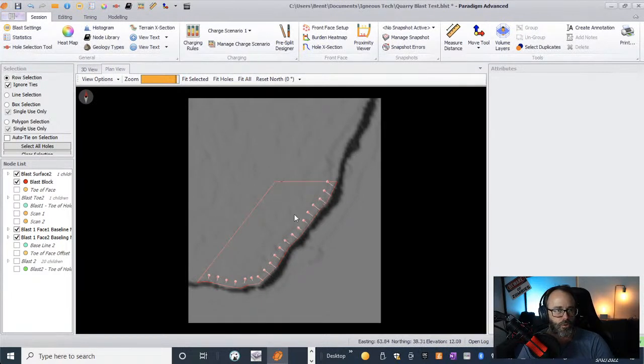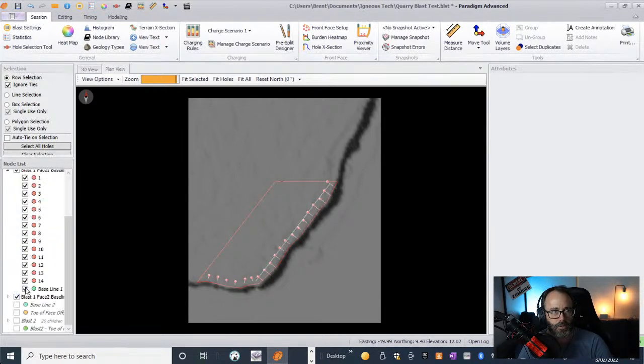So we set up our baseline scans, like I mentioned. We'd set up that line, and we'd scanned it from out here, and then we had done chainage and then offset off the baseline. So that was the method that we used there.